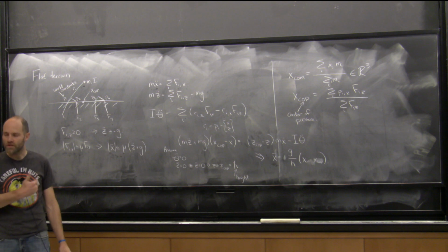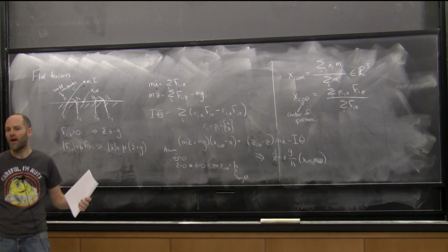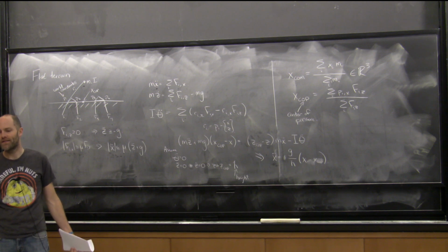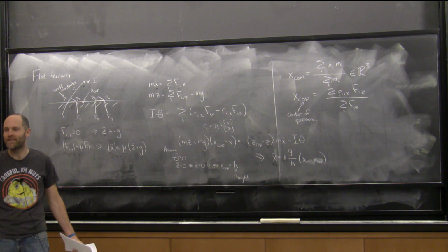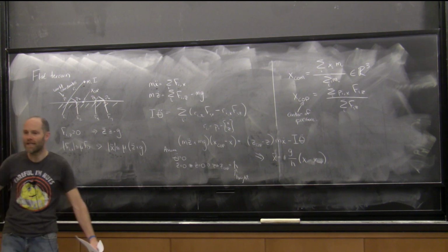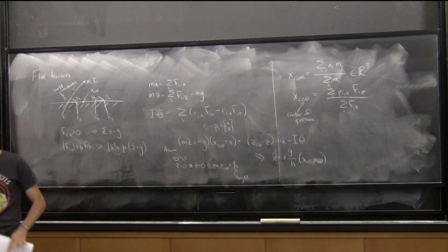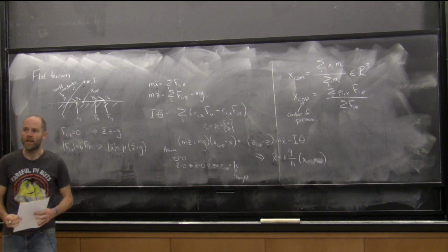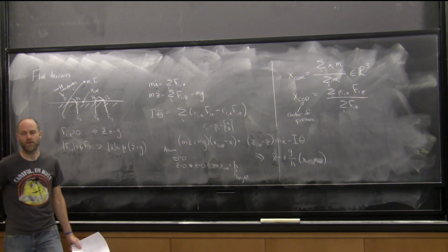But the generalization of this, which I'm going to define in a minute, is that what you care about are points around which you can summarize all of the forces on my body with a force instead of a force and a moment. I'm going to write that down in a second, but there's a generalization of center of pressure that's going to work better in your crazy cases. Even in the cases where I've got feet at different heights, there's a slight generalization of this. But it's simple to think about center of pressure, and it works really well for flat ground.